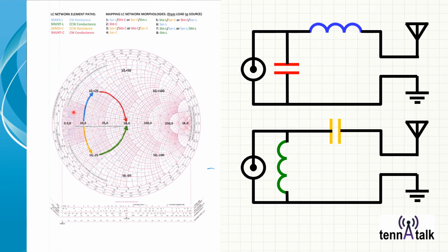Now, if I was off of the pure resistance axis here, then you would want to use different values of that. If I were starting here, it would be a smaller series L component. Now, if I were going from here, I would prefer going the shortest distance possible, because smaller LC values give me a more efficient match than going all the long way around here like so.